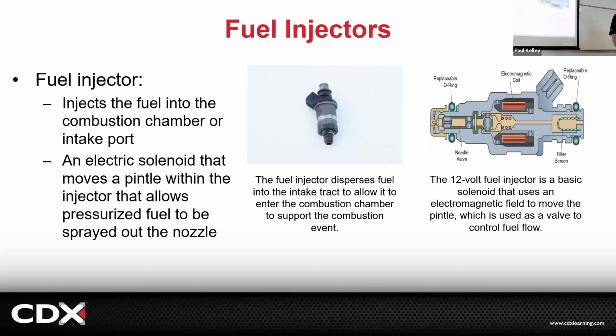Electrically, if they fail, though, it won't tick at all. And you can't really fix a coil winding in here. If that's the case, it's done. But what if it's not getting the 12 volts and ground from the PCM? We might have an open wire. Maybe a mouse chewed it, right? So there's a lot of different failure points.